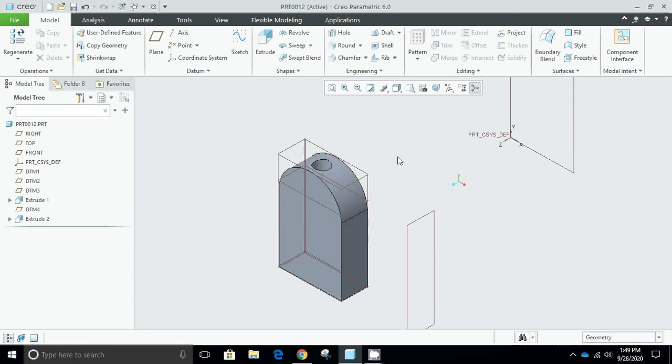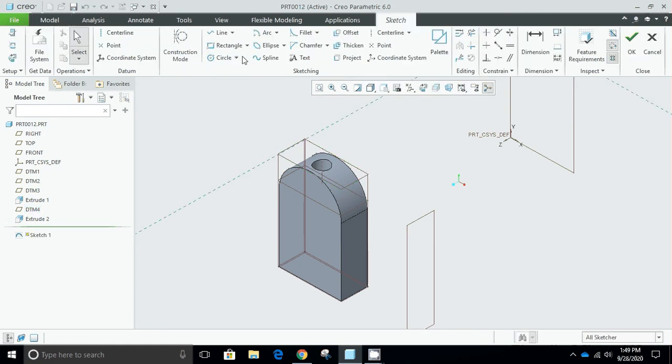In the same way, there is another type of plane which is the angular plane. How to create a plane at a different angle? In order to do that, we have to first, for example, this is the reference plane, and on this plane I have to create a plane which is at some angle. So I will first have to sketch a line.